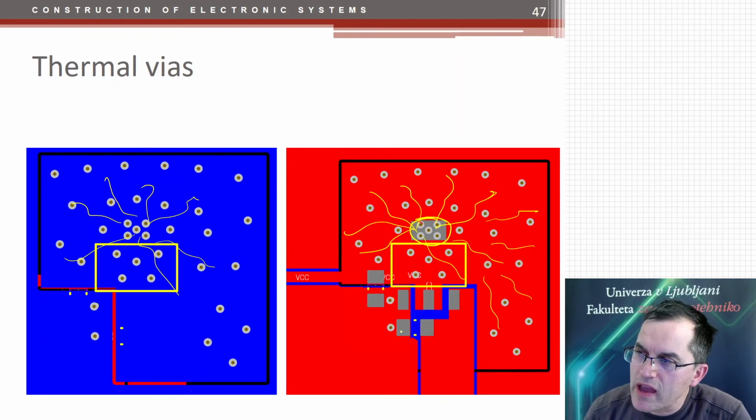Well, you can also have larger areas whenever you can, because even though you don't need them here at the input or here at the ground, you can still provide them. The larger the areas, the more the cooling. And I'm talking about areas of copper.